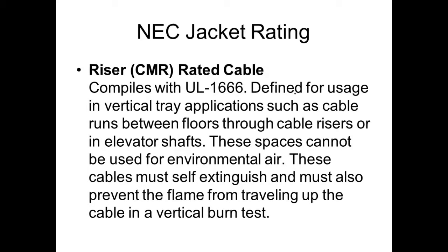CMR, this is riser cable. Riser cable is cable where the jacket's designed so you can run that stuff vertical. Complies with this UL listing, which defines uses in vertical applications such as cable runs between floors, through cable risers and elevator shafts. The space cannot be used for environmental air, so we can't run it through an air conditioning duct, right? Because if it catches fire, these cables must be self-extinguishing and must prevent flames from traveling up the cable. So that means even if they do catch on fire, they're supposed to extinguish themselves. And usually flames move what? Up.